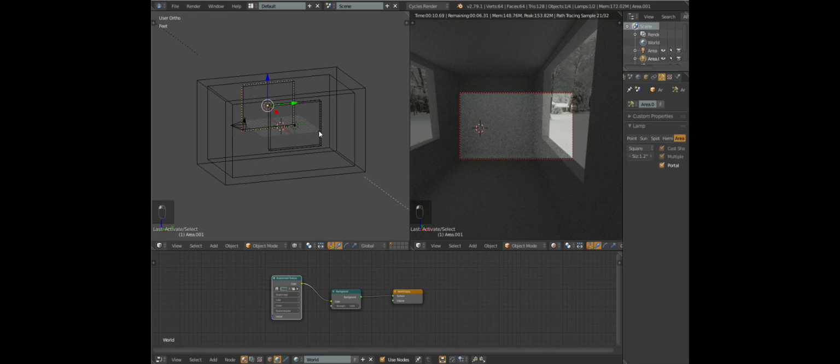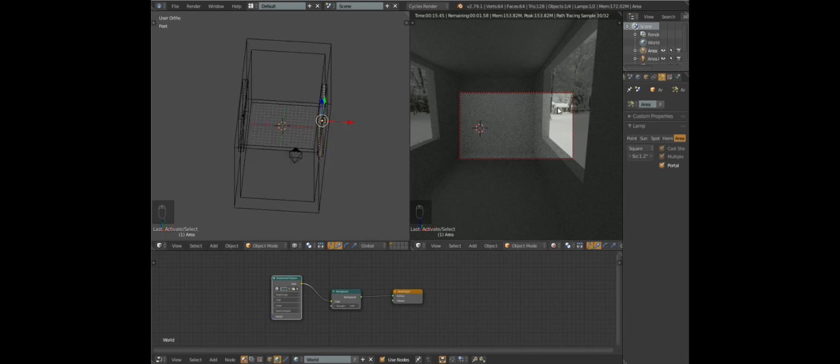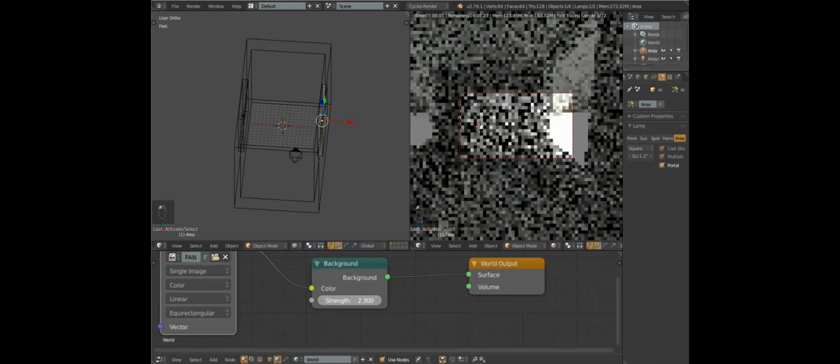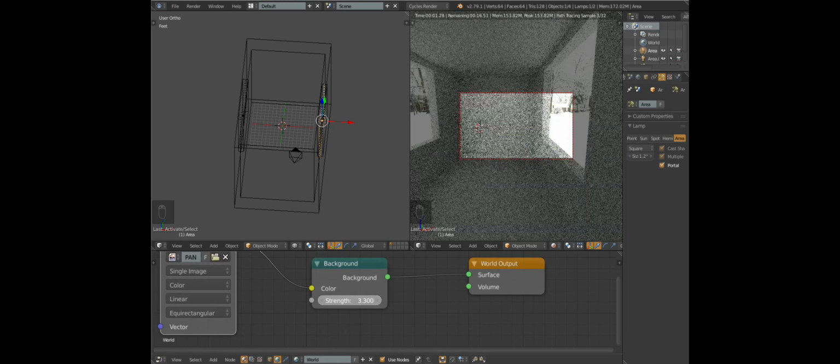If we do S and Y, we make it a little bit deeper. Now you can hit G to move it over to a corner here, maybe. Looks relatively nice. Then in front view, hit E and then Z to move it down wherever you want the height of the table. If it's an end table, it might be below the window, or you can put it kind of close to the window. Wherever that is, that will add edit mode.